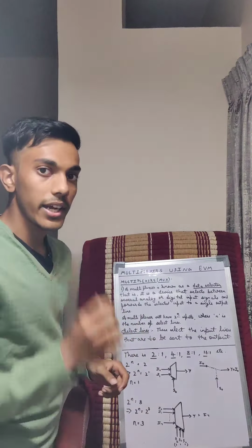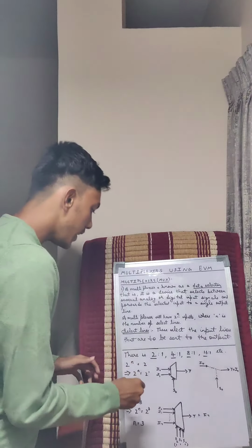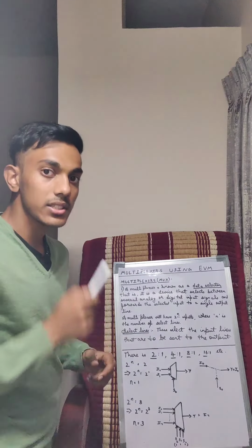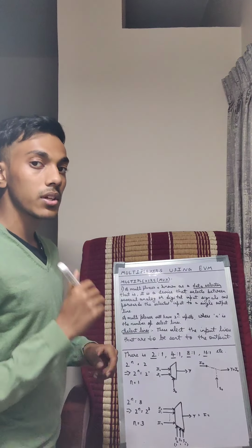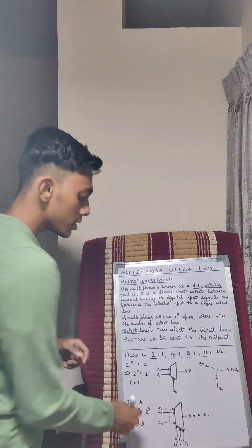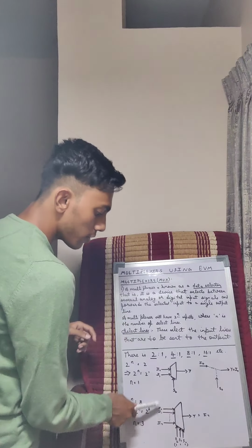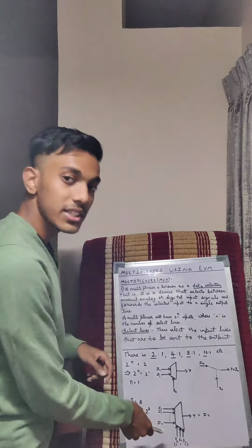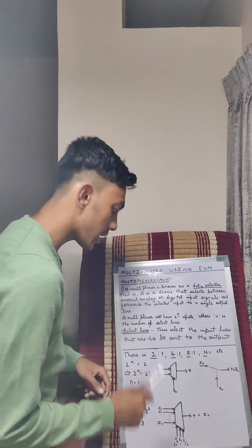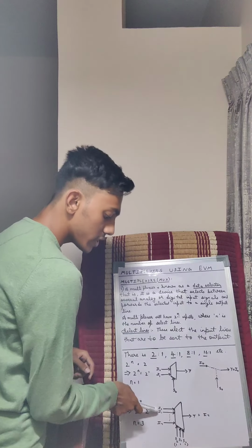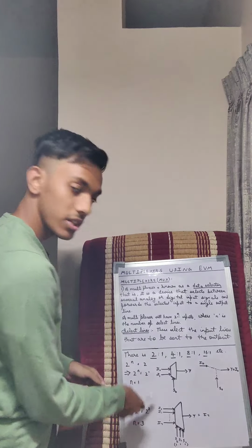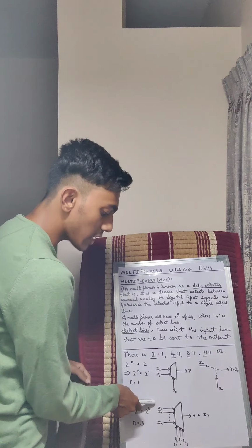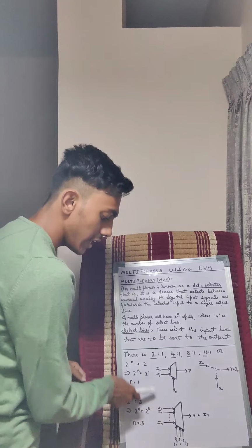Again, equate 8 to 2 power n. Write 8 in terms of powers of 2, that is 2 power 3. That means the value of n, which is the number of select lines you must consider, is 3. So, when you look at this diagram of a multiplexer, this is S0, S1, S2. How many select lines do we have? We have 3 select lines. And how many inputs? We have 7 inputs, right? Actually, there are 8. Here, I7 doesn't mean 7 inputs. We start with I0, so I0 to I7, 8 inputs will be there.